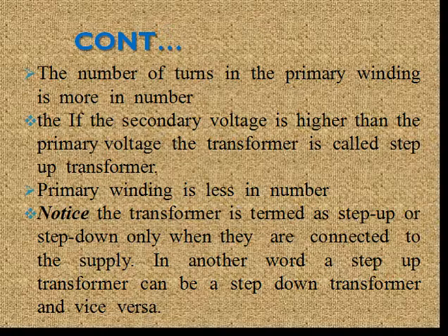Notice, the transformer is termed as a step up or a step down only when it is connected to the supply. In other words, a step up transformer can be used as a step down, or a step down transformer can be used as a step up.